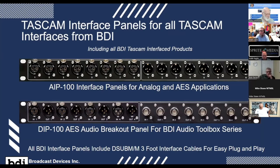We make these audio interface panels, which are our Tascam standard, and we developed them for our product line, but they will work with any Tascam interface. So if you have a piece of equipment that has a Tascam interface and you need to break it out to XLR or BNC, we make 50 ohm BNC for the composite stuff that we do, and we also make the 75 ohm, which I think is what's pictured there for the AES-3. A lot of the television folks that have AES-3 running around their plants like to use 75 ohms.